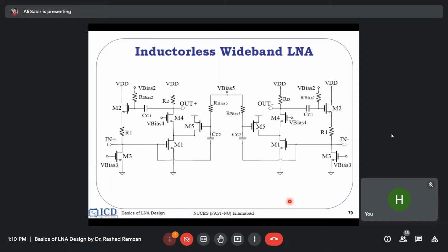But the bandwidth is reduced because of the additional capacitance and large transistor. To improve the bandwidth, there is a technique called cross coupling. In a differential signal, you have one node going up and a second node going down. If you tie those nodes with opposite capacitors, that's called a bandwidth extension technique.